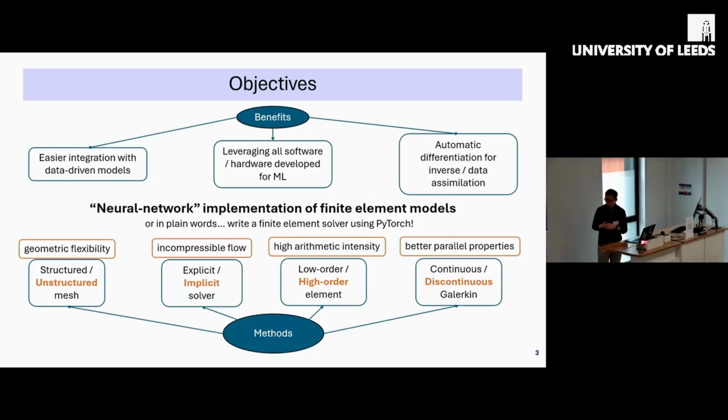And the second choice I made is whether I'm going to use an explicit solver or an implicit solver. I'm using an implicit solver here, although it doesn't have to be that way if you're solving a compressible flow. But I'm dealing with incompressible flow, so you have the pressure field that is coupled over the whole domain, so you have to use an implicit solver in some part of your equation.